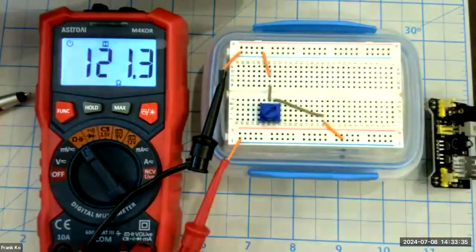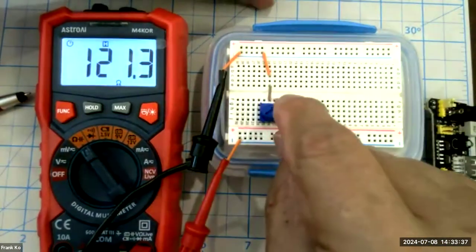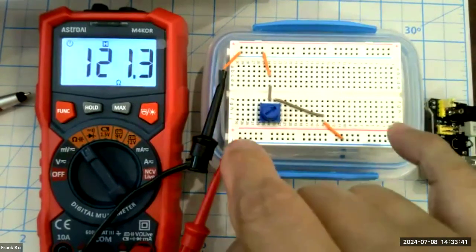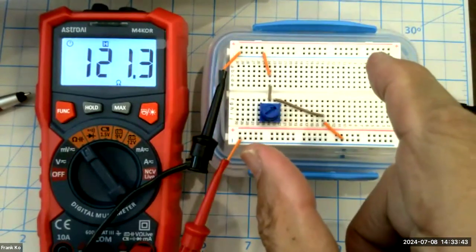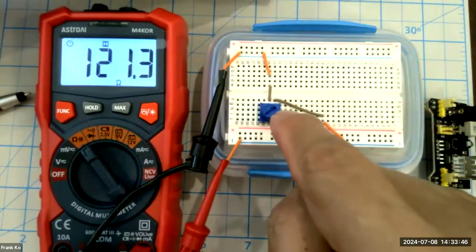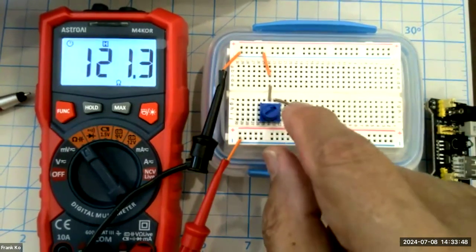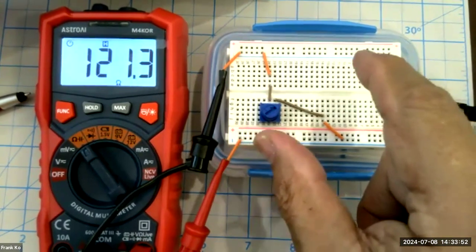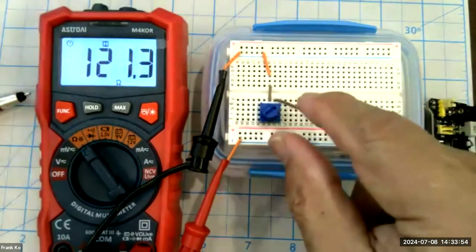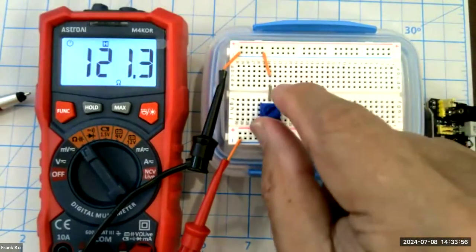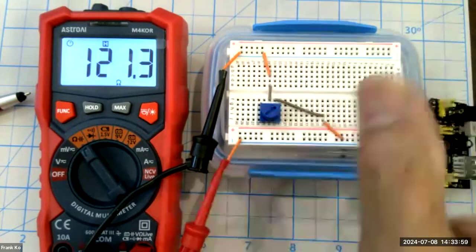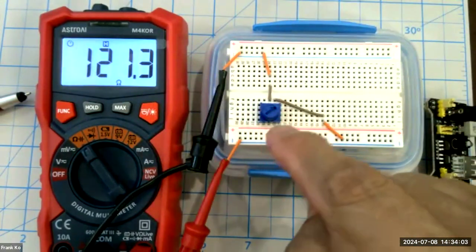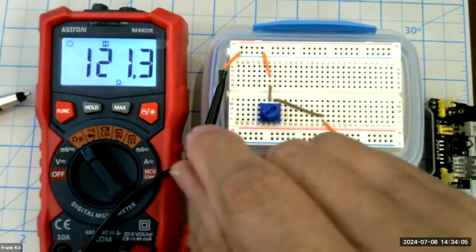Anyway, they could be a linear pot, meaning the change from one end to the other end of the pot is consistent, or it could be a tapered pot, which means that it is not consistent from one end to the other. One part of a rotation is not the same as the other part of the rotation on the other end. Anyway, let me just show you what we have here and how challenging it is with the single turn pot, how to get 167 ohms.